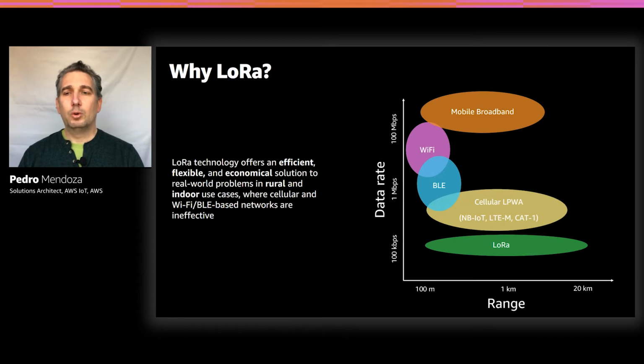In addition to LoRa, there are other technologies in this family. You can find as well Narrowband IoT, LTE-M, or Sigfox. As I mentioned before, these are technologies that are aimed for devices that are really constrained in terms of usage of power. That's why these devices need to run, for example, over 10 years and are typically battery operated. What makes LoRa special in the family of LPWAN technologies is the fact that it uses unlicensed frequency spectrum. As a consequence, it is possible for the LoRa users to set up their own private networks.